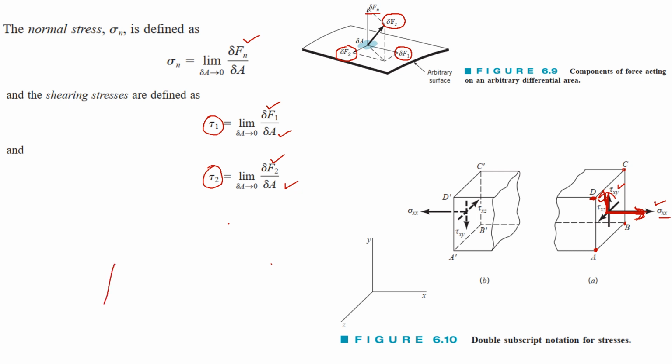If we take a cube and we say that this is a single fluid element, how will this fluid element behave and how will these stresses behave when we move from the center of this cube to these faces? How will these stresses change if we move from the center to these faces of the cube? So now we will be seeing the gradients of these stresses. These are the normal stresses and the shear stresses in the direction x, y, z, and we will write some terms and then add them up in terms of forces to get our surface forces. So now let's move on and do that.